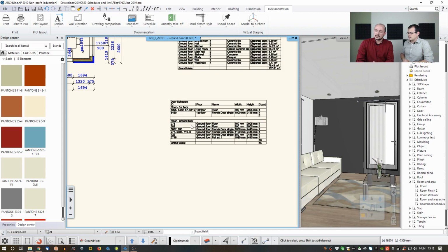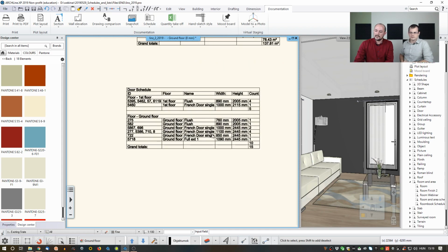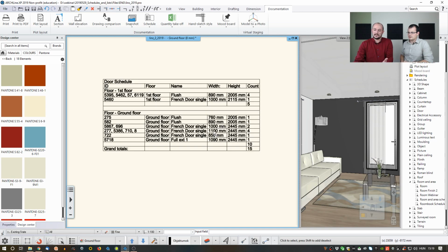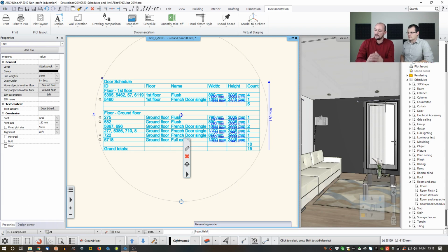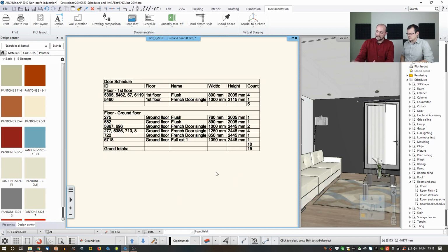The first option is, just as you mentioned, what happens if I'm not satisfied with the size of this? Now I realize that these should be larger. So I just click on the list and edit this value. Those are actually the windows in front of us here, so we will be able to see them very well. So I rewrite the size of this window in the schedule to something a little bit larger. When I do that, it's changing the size of these windows, and as you can see, those are enlarged on the drawing.